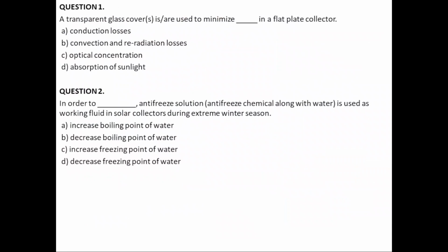There is a lot of literature which discusses the variation of the percentage of ethylene glycol with its freezing point. Glycerol is also one of the agents which can be used as an anti-freezing solution. If you add ethylene glycol or glycerol in water at a particular optimized concentration, you can almost achieve a freezing point of minus 60 degrees Celsius.